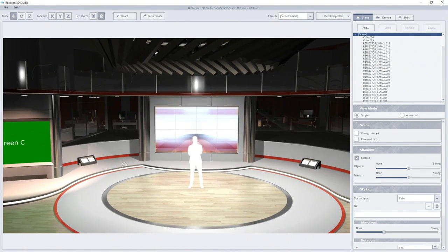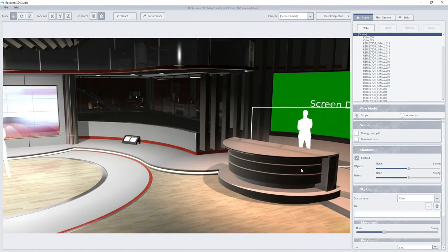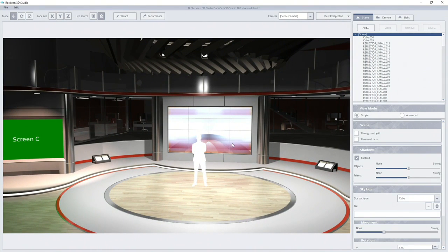Now you can jointly set a common shadow density for all these objects. Select Scene and go to the Object slider settings. None, that is highly transparent. Or strong, that is more distinct. The shadow density for all objects will also depend on the rays of the set light.